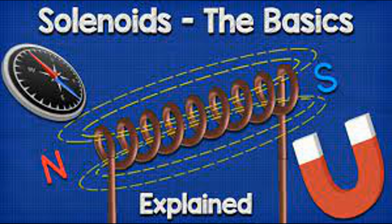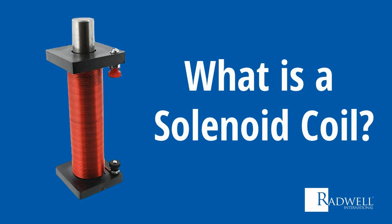5. Return mechanism, optional. When the electric current is turned off, the magnetic field disappears, and the core is no longer pulled toward the center. To return the core to its original position, solenoids often use a spring. The spring pushes or pulls the core back into place when the magnetic force is no longer active. In some cases, gravity or another external force may be used instead of a spring.